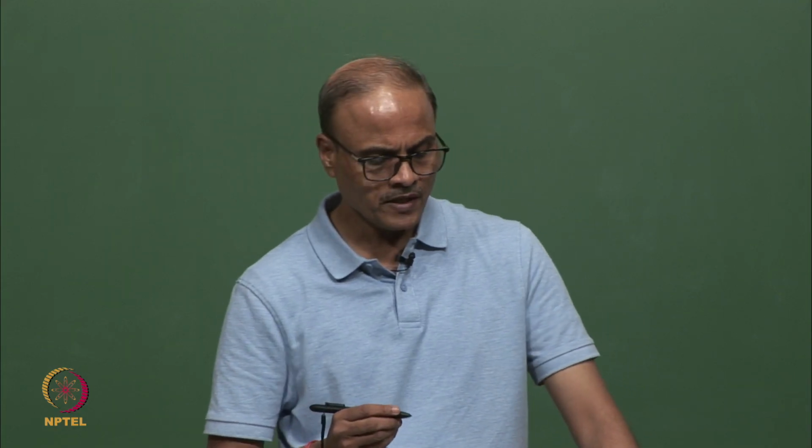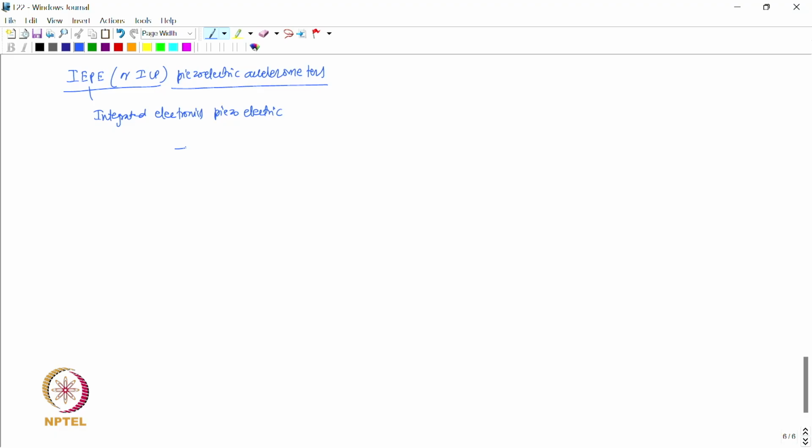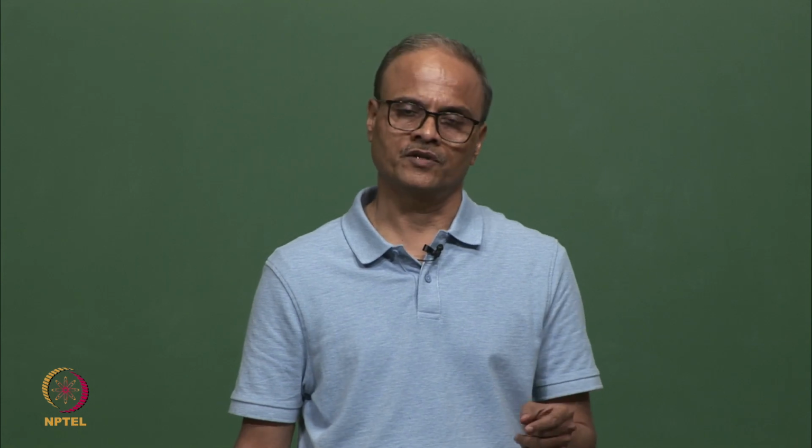So these IEPE types of piezoelectric accelerometers have a built-in charge amplifier. A small IC, which does the job of charge amplification, is built into the transducer itself.